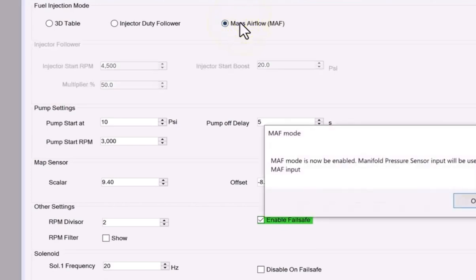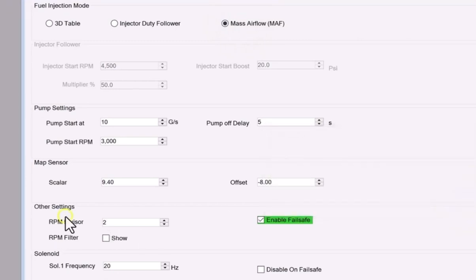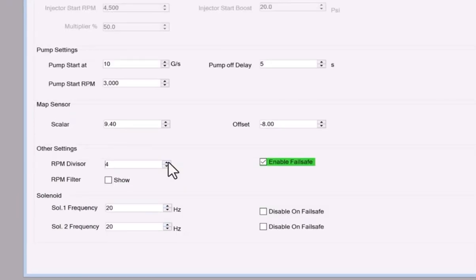Next up, RPM divisor. Frostbyte can determine the engine speed from ignition coil and coil on plug signals, as well as the fuel injector if it is the port injection kind. The divisor here allows you to multiply or divide the incoming signal until it matches what you are seeing in your car. Solenoid. As mentioned before, Frostbyte has two main outputs which can be used to drive low amperage fast-acting solenoids. These solenoids are pulsed via a PWM signal, and as such, we can use this section to determine the frequency for the solenoids.